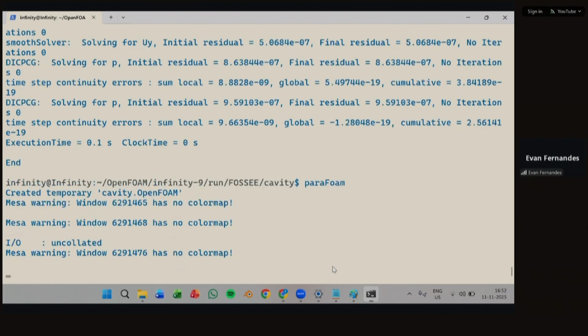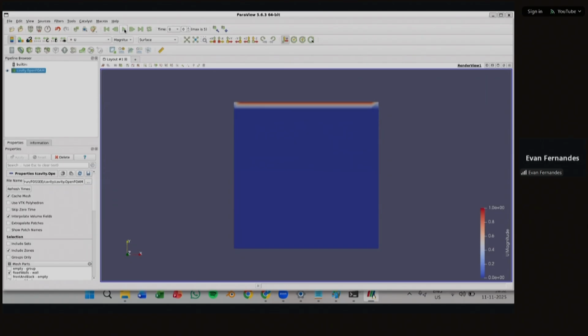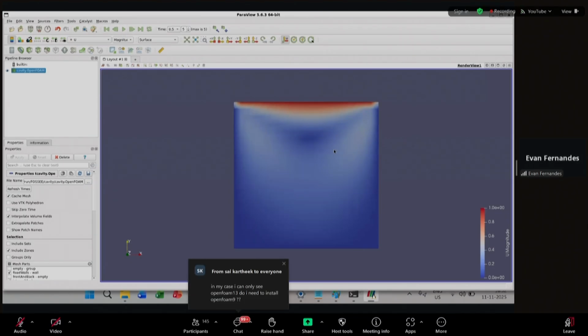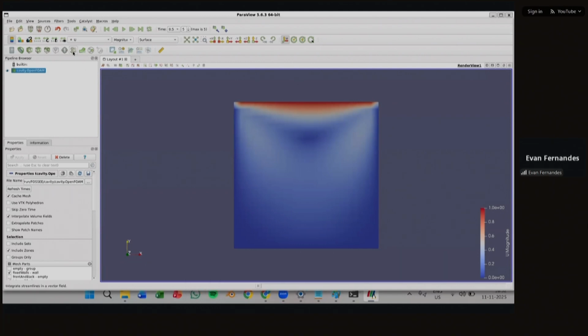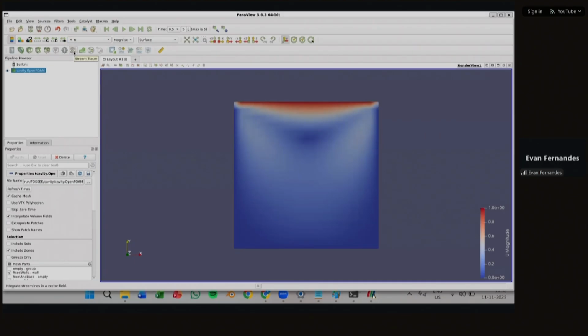Okay. Now, once it is open, on the top left you would have U, p and all that. This is where you can change the parameters you want to see. So we can see the whole simulation. Now this is your simulation. But you don't really understand where the recirculation and all that are. To view those, ParaView itself has multiple ways. From where you clicked your U option, velocity or pressure, just below that, you have a few of these options.